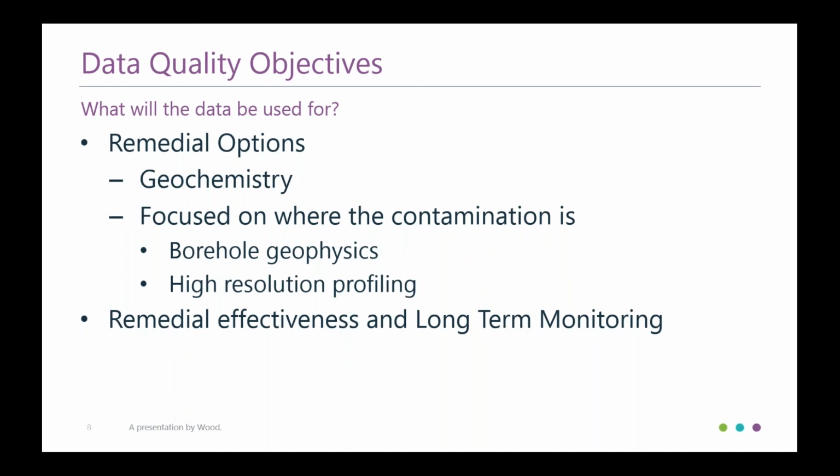And the nature and extent, you'll know where it is, but you may have well screens that are too long if you're using other wells that are already installed to try and figure this out. So if you have a 20-foot well screen that's spanning several types of geology, and you have a couple of transmissive units in there, it doesn't really tell you where that is. And if you start treating over that 20 feet, it may be less effective than if you figured out, oh, it's the top one, which is down 10 feet. And if you can focus on that, your remedial treatment will be much more effective.